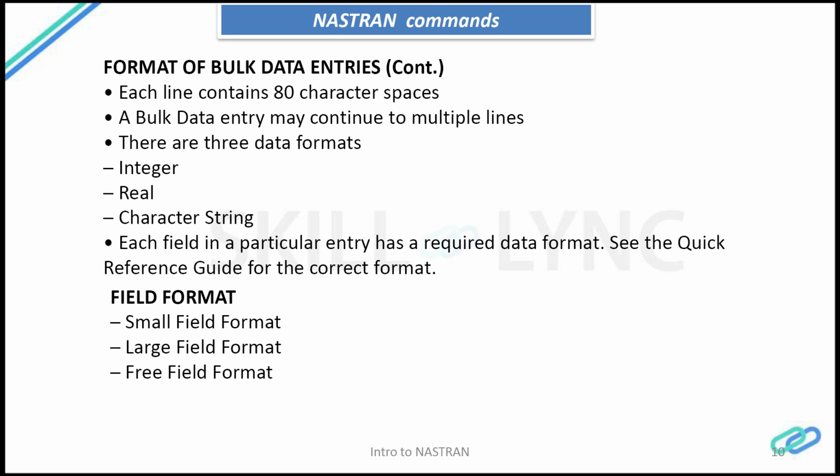And again, the format of the bulk data entries. When I say bulk data entries, those are all the model data, or all the lines within the bulk data section of the BDF file. Again, regarding the format of the BDF, there are three types, which are small field format, large field format, and free field format.